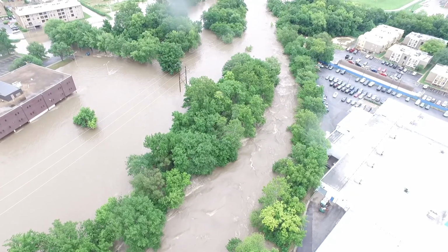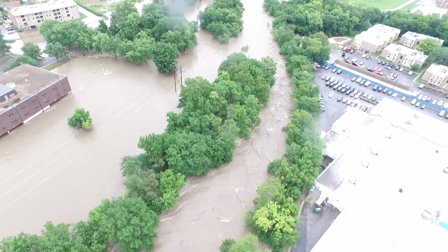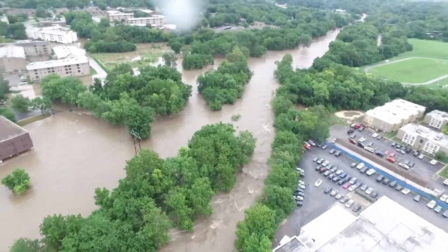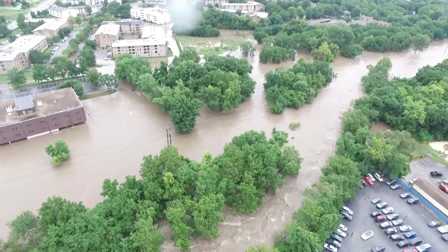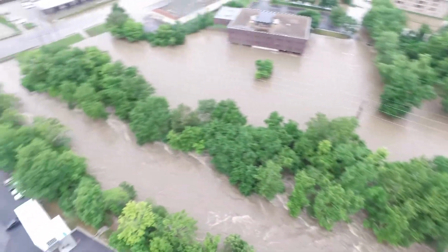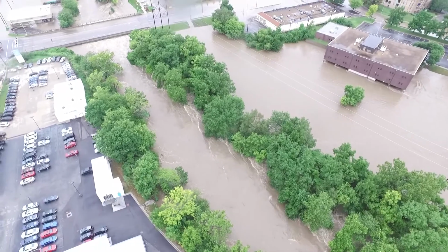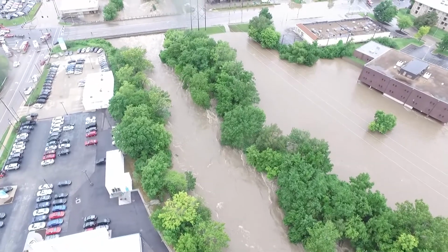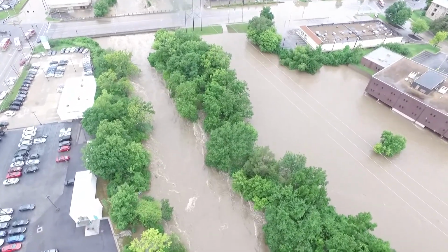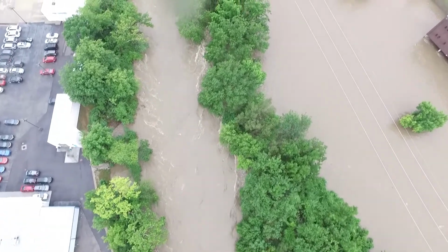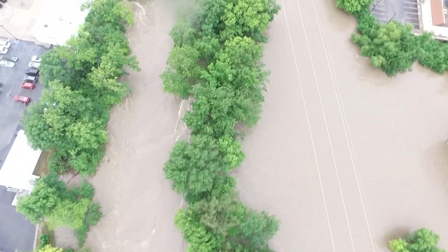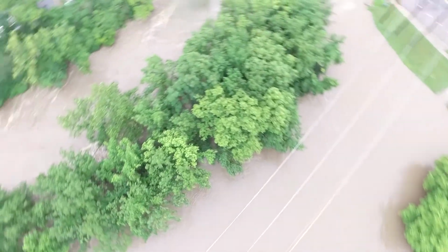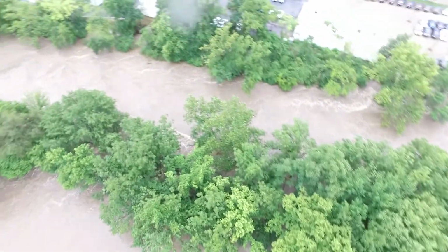As you can see from the video, there's been encroachment on the stream by development, both residential and commercial. These were two rainstorms that occurred within a couple of weeks of each other. This is one of those rainstorms in 2017, and it produced flows that were significant in the creek, however, not what the city or the folks around here would expect to see in what we typically use as our benchmark for maximum flood event, the 100-year or the 1% annual exceedance flood event.